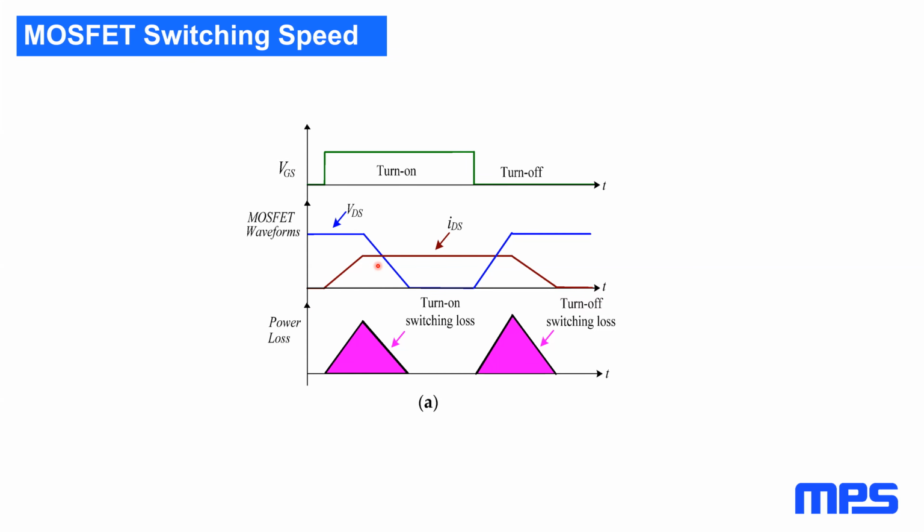How to protect a MOSFET in a half-bridge configuration with drain overshoot? That can be a little difficult. You can use transient voltage suppressors, TVSs, for example. You have to be careful because they aren't a very precise breakdown, so you have to have a fair amount of margin in the MOSFET rating as well. In some cases, RC snubbers can be effective to do that as well, especially if there's ringing.